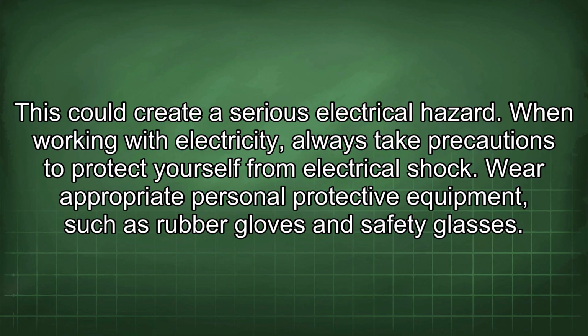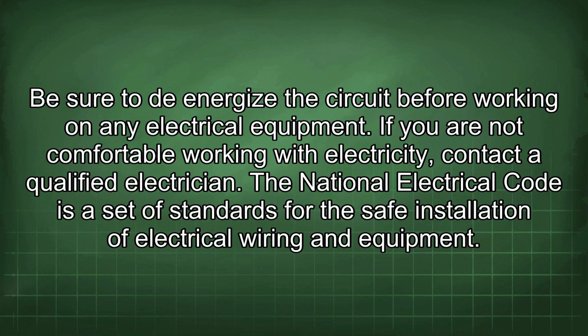When working with electricity, always take precautions to protect yourself from electrical shock. Wear appropriate personal protective equipment, such as rubber gloves and safety glasses. Be sure to de-energize the circuit before working on any electrical equipment. If you are not comfortable working with electricity, contact a qualified electrician.